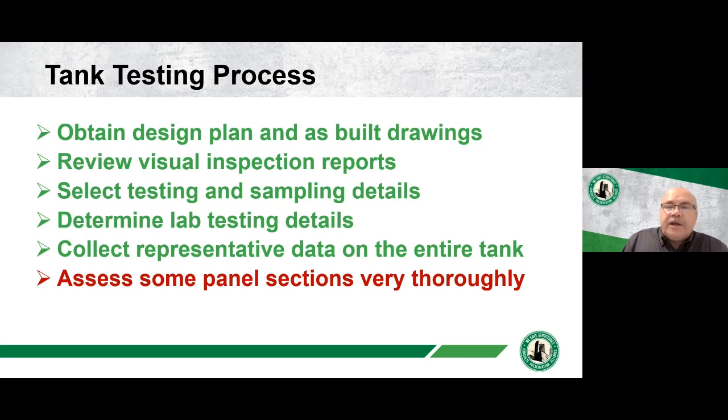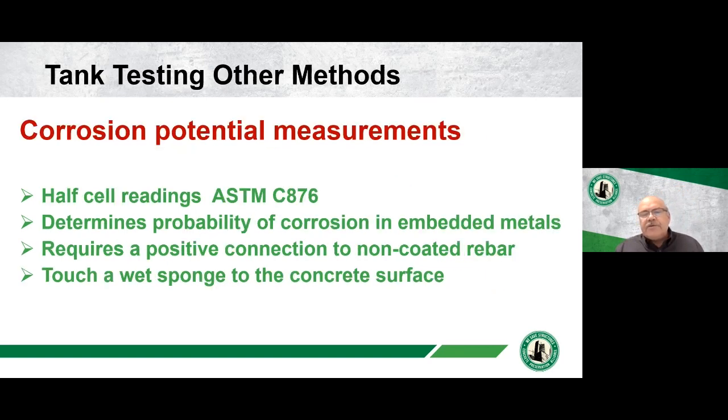Do want to share a little bit on tank testing. Obviously, we want to look at the plans, make sure that things were built the way they were designed. There's visual inspections that can be done, testing and sampling. Some lab testing is very valuable, and we want to get some representative data on the whole tank and then do a deeper dive on certain sections of the tank.